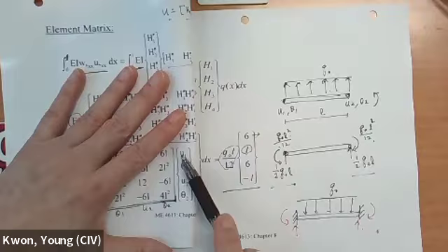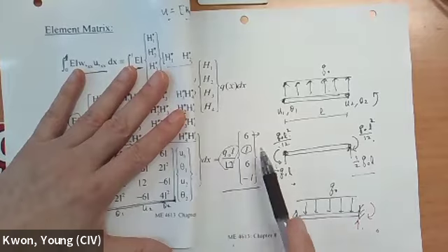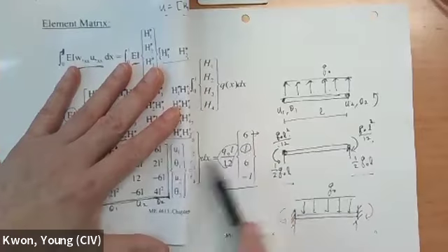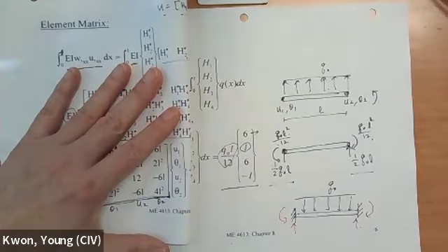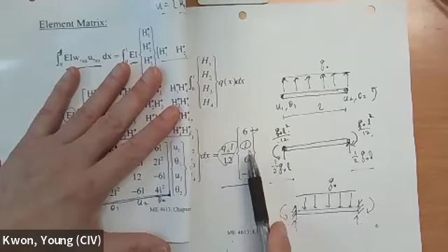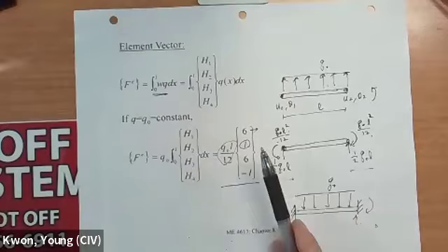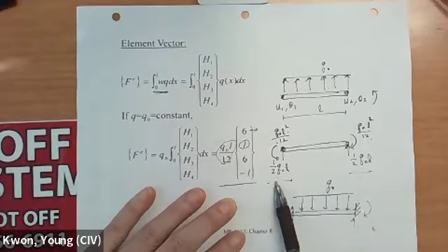Force times displacement is energy, right? The work or energy. And moment times slope is also work. So they call it energy conjugate. In other words, every product should have the same meaning of energy or work. Okay. So force, moment, displacement, slope. Anyhow, this is represented in this kind of way.